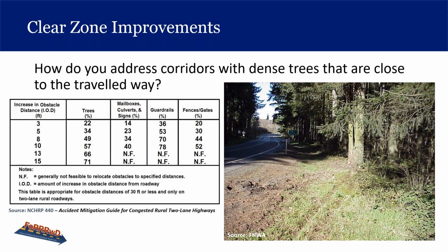And of course, the other question was, what else can you do in that curve if that's a problem? We've looked at other countermeasures for curves, like adding friction. It doesn't look like there's any chevrons or arrows in that curve, or maybe it doesn't even have an advanced warning sign, things like that.